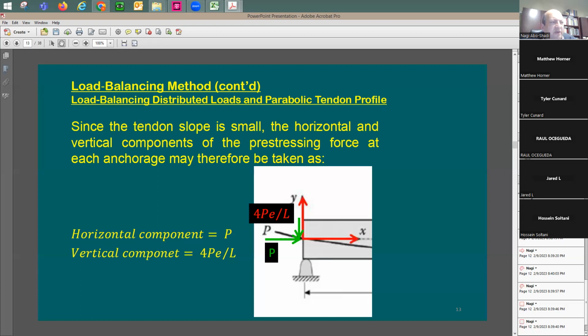All right, so what is the shear? The shear is going to be a force. It's trying to take this block of the beam and bring it down. Let's say here's a beam, right? And this is going to be the shear location. It's trying to bring this down, correct? It's going to be something like this. As if I'm pushing this down and pushing this up, correct?